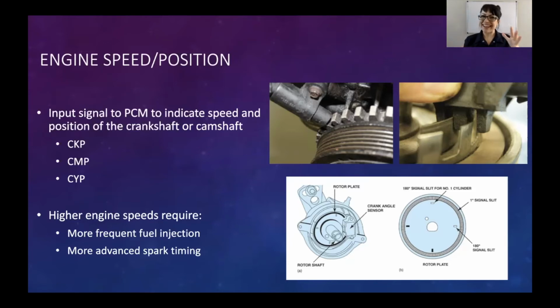That's a little bit ridiculous, but this optical sensor is kind of like that. It uses a photodiode and an LED to pick up light or not pick up light. This one's going to be a 3-wire as well, and it's going to produce a digital signal.